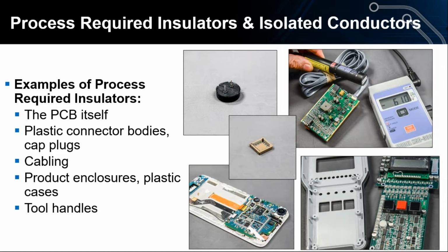Non-process essential insulators. I'll do a demo on that later, but you know, we see people have water, pocketbooks, and you name it on workbenches. And with the new 2021 version of S20.20, the requirement is for non-process required insulators to always be a foot away from devices, whether or not they have less than 2,000 volts or not.